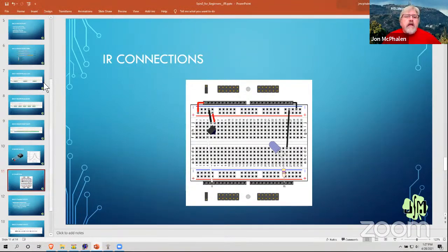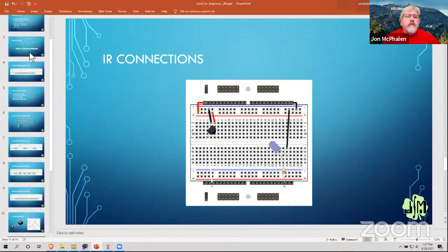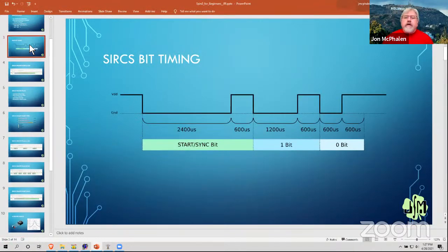Okay. If we go back quickly to this slide, you'll remember that the bits coming out of the IR sensor are low-going pulses. And what that suggests is that at the core of any of our code is the ability to measure a low-going pulse. In fact, we've been doing IR. The nice thing about Sony IR is, because of the simplicity of its protocol, it's very durable, which makes that really nice. But very simple processors can handle it too, within reason.